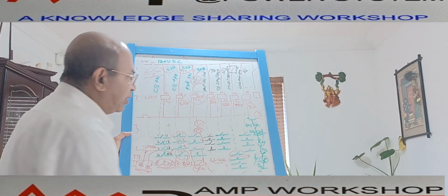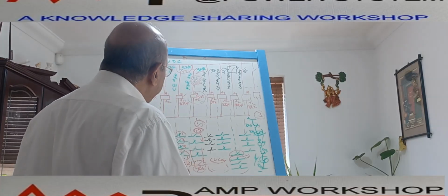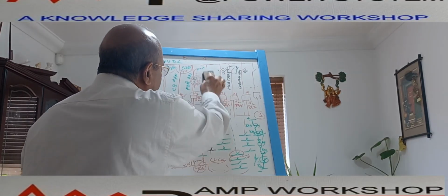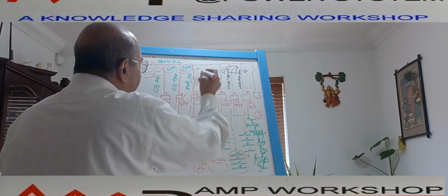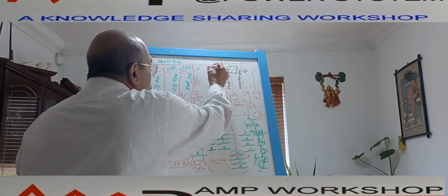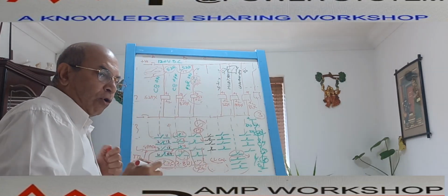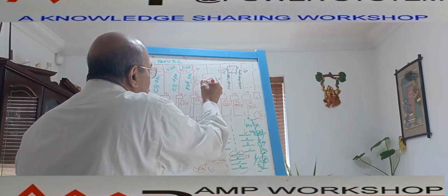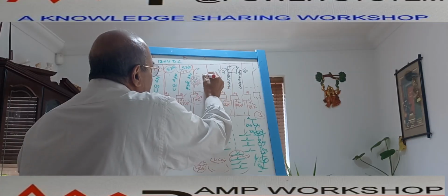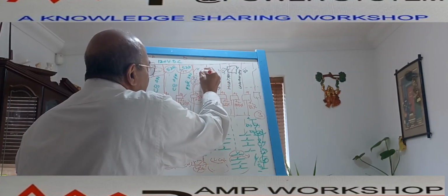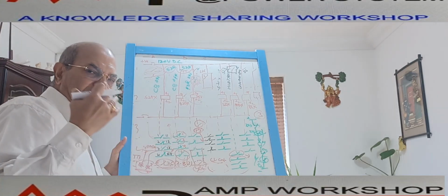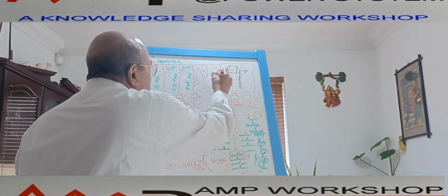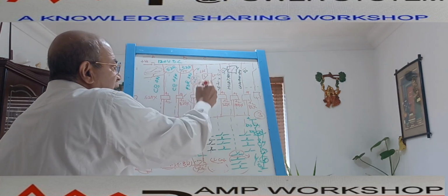I told you about the SF6 circuit breaker. In case of an SF6 circuit breaker, if the pressure is low, suppose we want to monitor the SF6 circuit breaker. So what I will do over here, the SF6 circuit breaker pressure switch is suppose low. Suppose for these two conditions, low and low, we want one contact. So we'll use one low contact and another low contact. This is SF6 low. The SF6 chamber gas pressure is low and this is low. So low and low, both auxiliary contacts I will use in parallel.